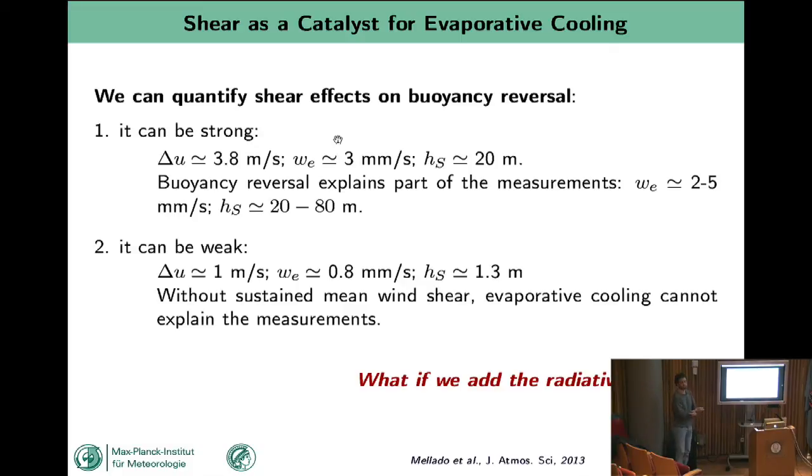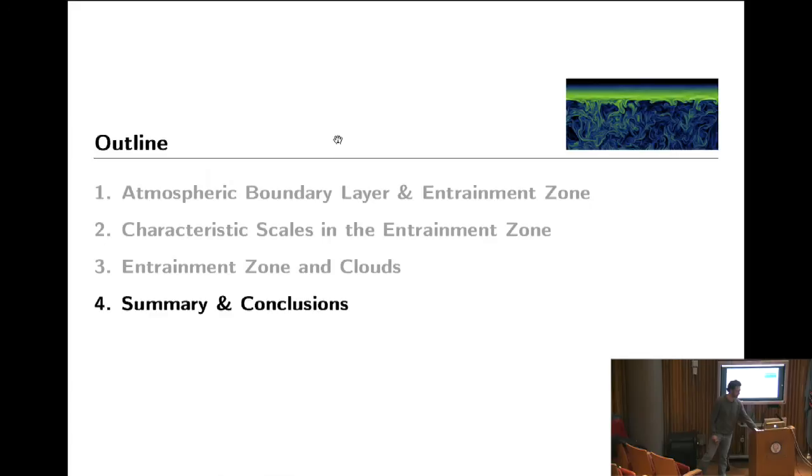This already tells us why the LES was having that many problems. Large eddy simulation was enhancing mixing spuriously because of the subgrid scale model, and that was just artificially cranking up the effect of evaporative cooling. Right? It is simply, if you have an additional external mixing for evaporative cooling, you increase very much the effect of evaporative cooling. That is the problem of large eddy simulation.